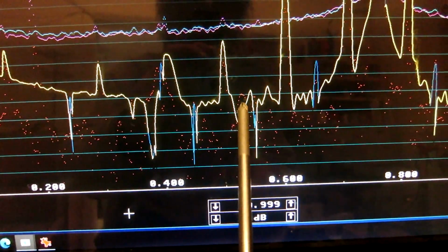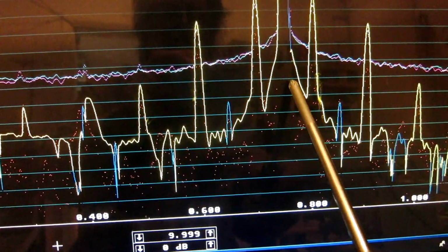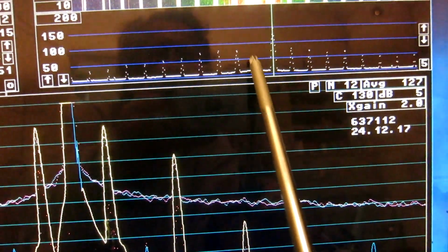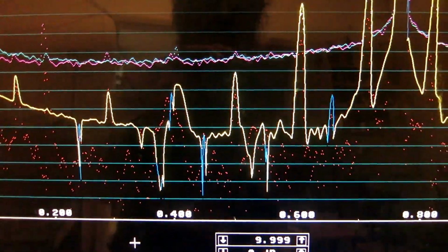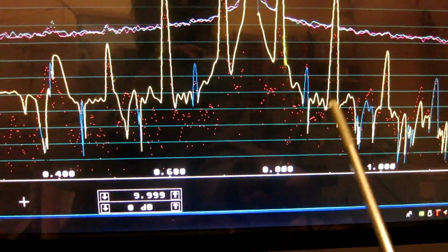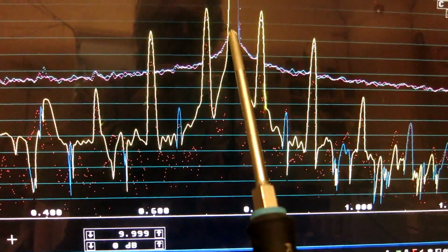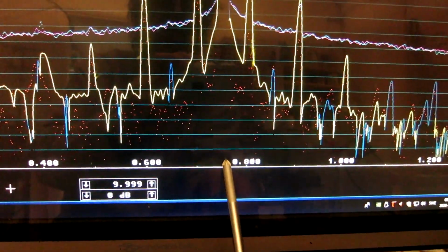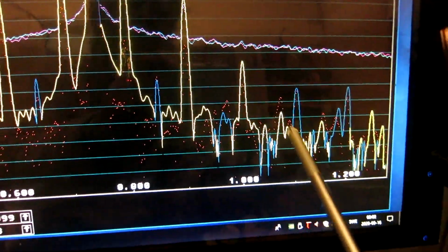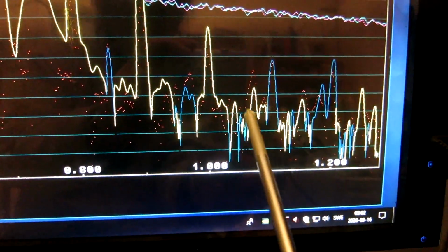And then at even wider separations I start to see the DC, the frequency 0, means the peak here. I have a direct conversion system, so I cannot see the phase noise around. Here is the offset frequency, 760 Hertz or something like that. But at some even larger separation, then I can again see.